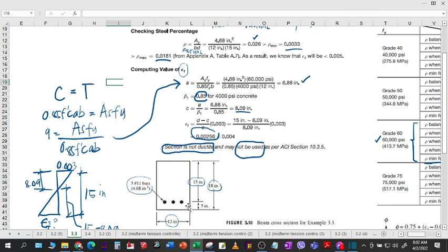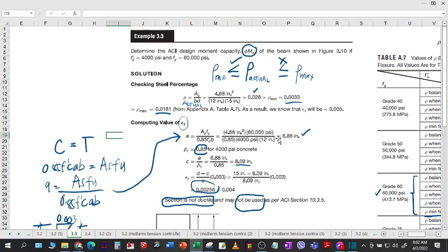By that, you can see that the section is safer because the occupants of the building will have some time to evacuate because the symptoms are showing. Whereas if the design is compression controlled, when failure happens, the building will just collapse, and the occupants will not be able to evacuate. So that is how to solve this problem.